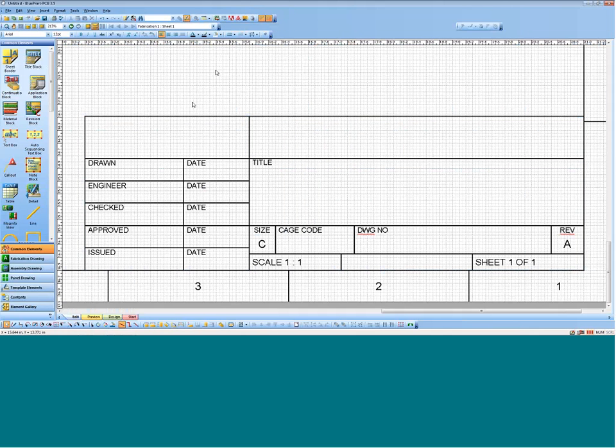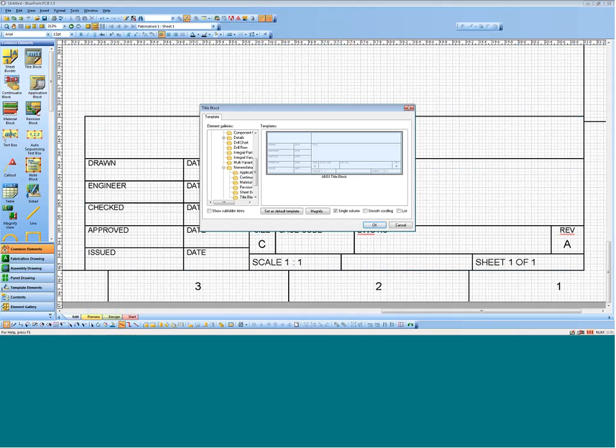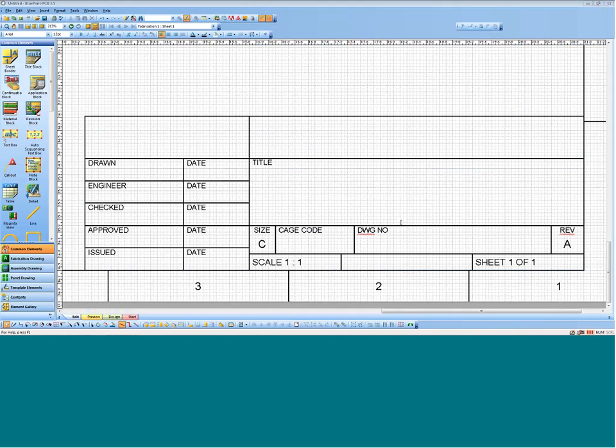Once I make a modification to any of these sorts of things, I can save them off to the gallery. And when I click on title blocks, if I have more than one, they'll show here, and I set one of them as the default, and that's the one that gets populated when I do a drag and drop. There's some intelligence to these title blocks. First of all, they know they go in the lower right by default. As you can see here, it knows it's Rev A. That's done through our document variable manager, and I'm going to show you that here.